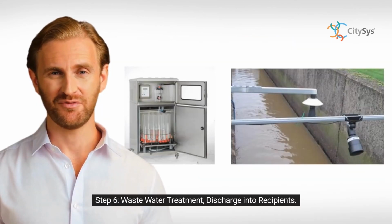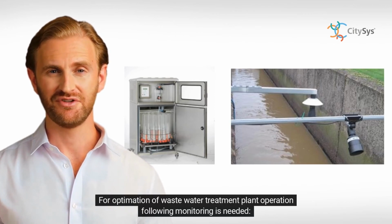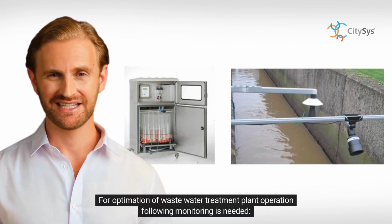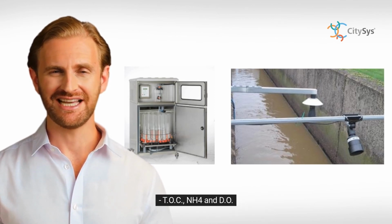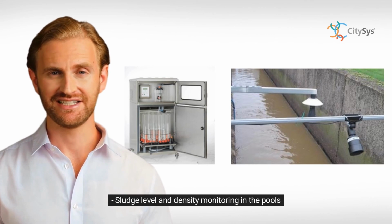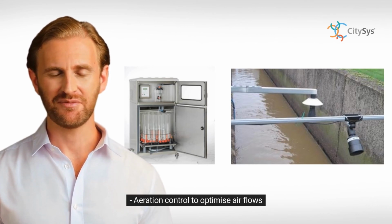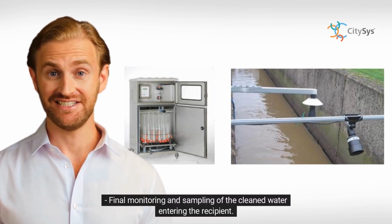Step 6. Wastewater treatment, discharge into recipients. For optimization of wastewater treatment plant operation, the following monitoring is needed: COD, BOD, ammonium, phosphate, turbidity monitoring on inlet to control chemical treatment, TOC, NH4, and DO monitoring in the nitrification and denitrification stages, sludge level and density monitoring in the pools, aeration control to optimize airflows, biogas monitoring in the anaerobic treatment, final monitoring and sampling of the cleaned